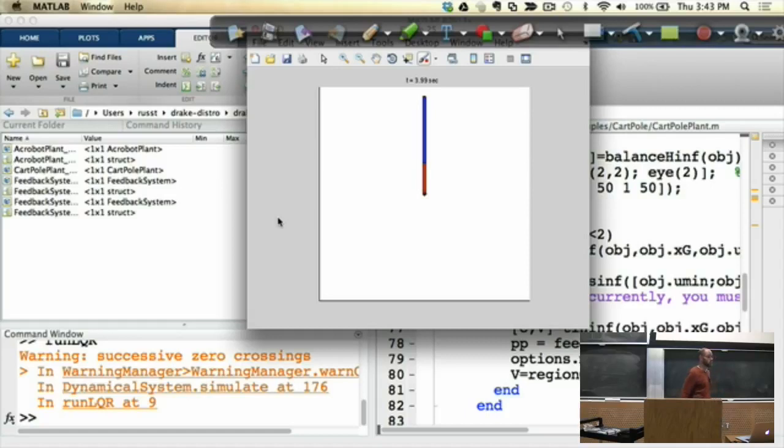It seems the result that we got indicates that the controller is linear, like a linear function of x. So doesn't that mean that it does correspond to placing certain poles? It absolutely does. That would be another thing to say: we're doing pole placement too, but instead of choosing K1 and K2 directly, we're going to choose Q and R, because it's an easier way to choose those same gains. That's a more friendly way to say it, I guess.